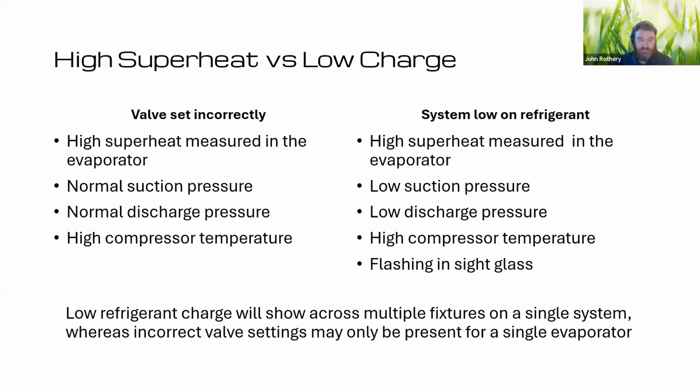Refrigerant logging? Yeah, I have done, to be fair. A lot of it should obviously be designed to push it out of the gas cooler. Keep the gas coolers clean, check if you've got false load on the gas cooler for heat boost, that sort of thing. Check they're not iced up. It does happen, and you can get the logging. Generally, if checking charge, if you lose gas, you lose oil as well, so it's always worth comparing the two.